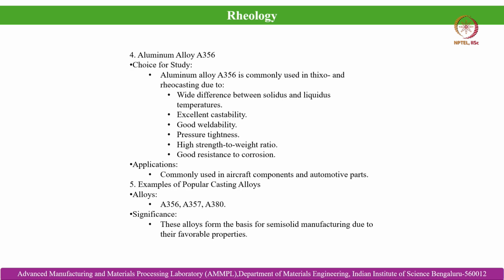The rheological evolution and also die design for semi solid casting are connected, and of course, rheology is equally important for conventional liquidus casting also. As I told you, when the superheated melt flows within the die cavity, at pockets and locations solid formation already starts. So, it becomes important to investigate the viscosity evolution of the solidifying melt, so that we can achieve solidified parts free from defects.